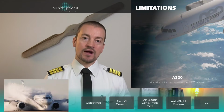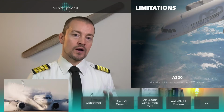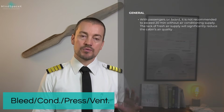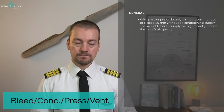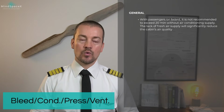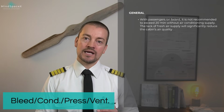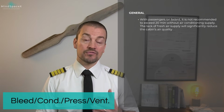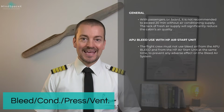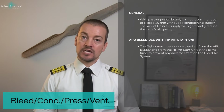And that was it on the aircraft general limitations. Let's jump into some of the limitations that are placed on the specific individual systems, starting with the bleed, pressurization, and ventilation system. For the air conditioning system, a general limitation recommendation is that with passengers on board, it is not recommended to exceed 20 minutes without air conditioning supply. The lack of fresh air within the cabin will significantly reduce the cabin air quality. APU bleed with the use of a high pressure air starter unit is prohibited.